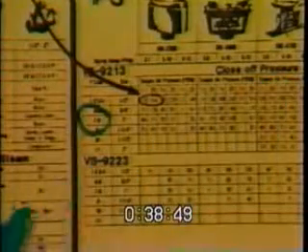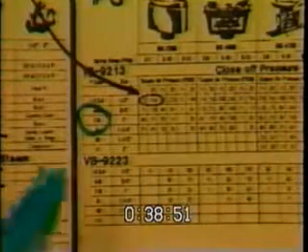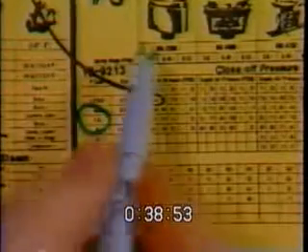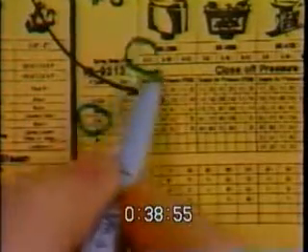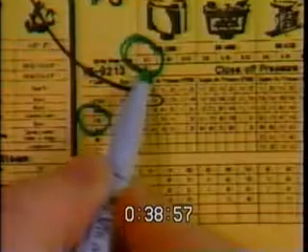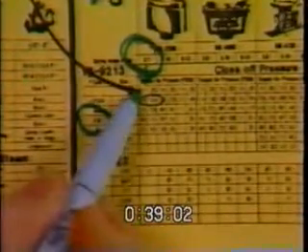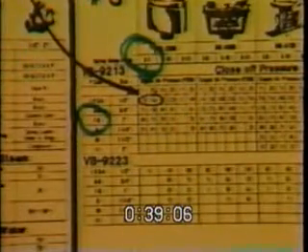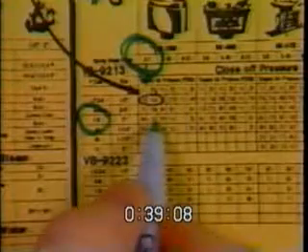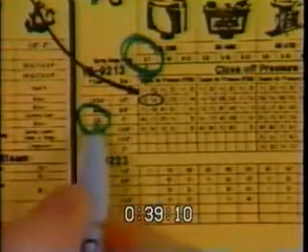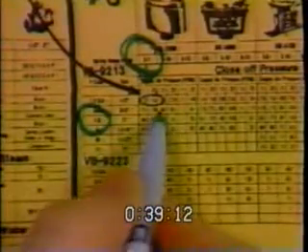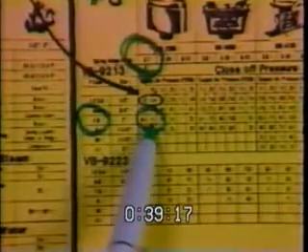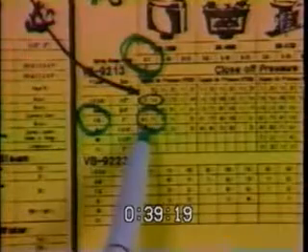Now the valve I wanted was a normally open. And a normally open valve, by itself, will want a 3 to 7 or a 3 to 8 spring range. So that's this column. Also, it shows the 15 or 20 psi supply. In our example, we have a 20 psi supply. Going along here, you can see that my close-off pressure rating using this actuator is going to be 75 psi.